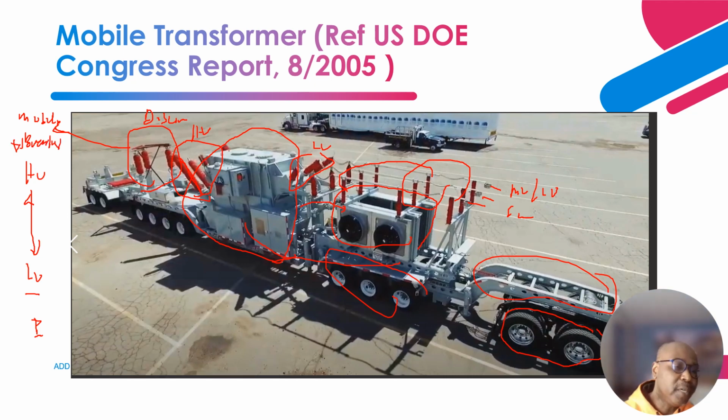Okay, so this is when it becomes necessary to have a mobile high voltage breaker to integrate to this side, so that you should be able to switch in and out this breaker. If there's a fault during operation of this mobile switchgear, you should be able to trip that breaker and isolate this mobile sub.